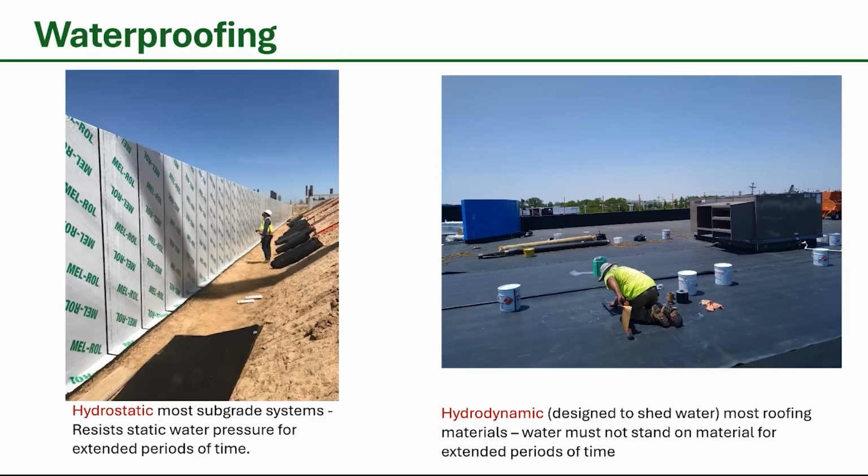Hydrodynamic waterproofing, typically looking at things that shed water, treats water as a live load. So your roofing membranes, your sidings, all of those things, that's hydrodynamic waterproofing. And why would you make that hydrodynamic versus hydrostatic? Well, we're already optimizing the roofing for UV resistance. That's not a concern when you're burying it below ground. You're optimizing the roofing membranes also for economy, being able to be affordable. The two are very different.